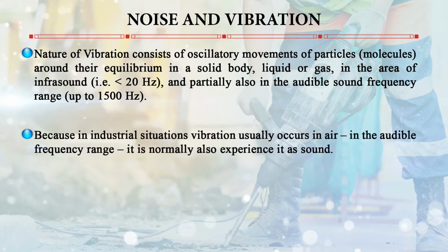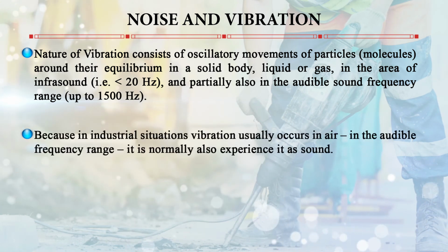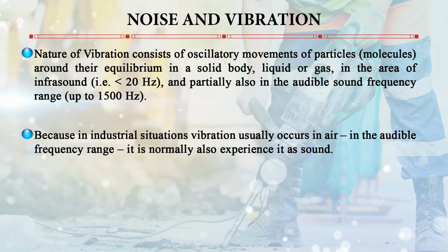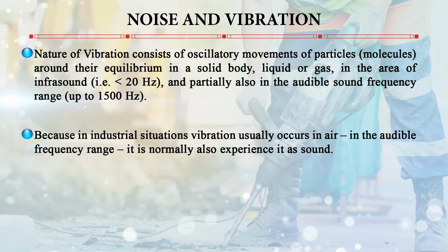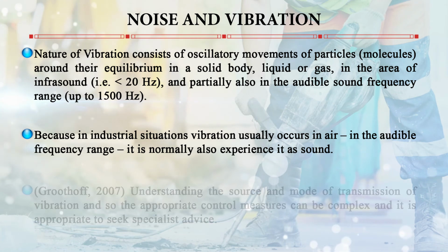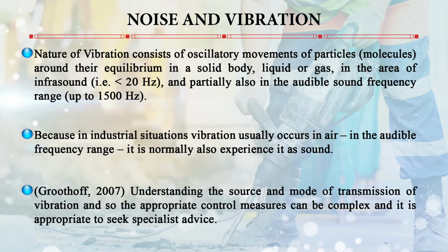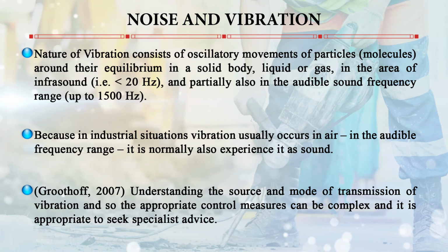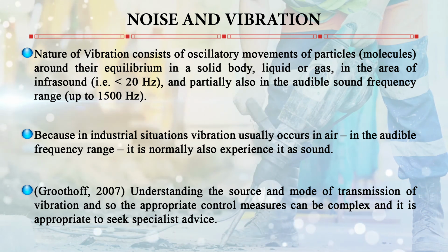Because in industrial situations vibration normally occurs in air in the audible frequency range, it is normally also experienced as a sound. Understanding the source and mode of transmission of vibration, and so the appropriate control measures, can be complex, and it is appropriate to seek specialist advice.